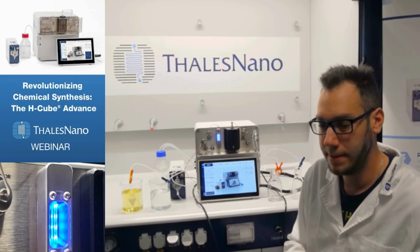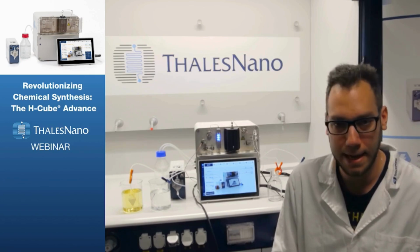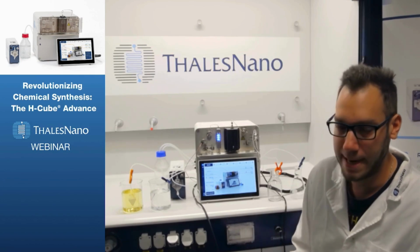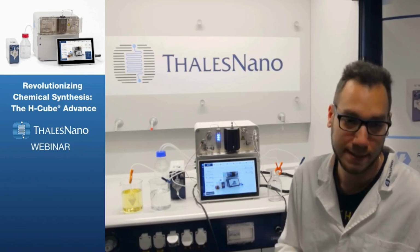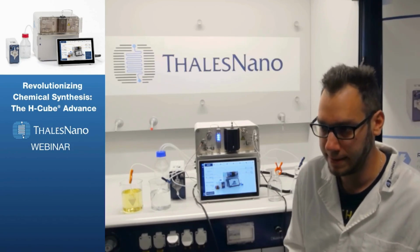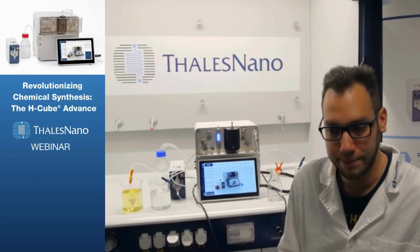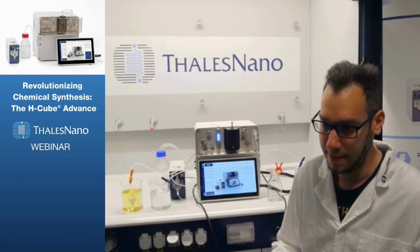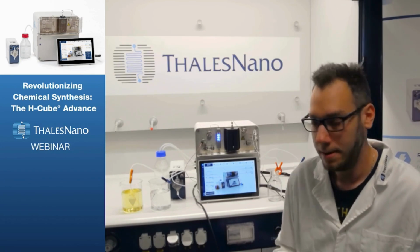So this is a see-through cell that's illuminated by a blue LED light that allows you to visualize whether the hydrogen gas has already entered the flow line or not. Of course, if the hydrogen production is turned off, you won't see any bubbles. It's possible to use the system with liquid-liquid reactions only. But if you're doing a hydrogenation, or if you are using the external gases option, you will be able to